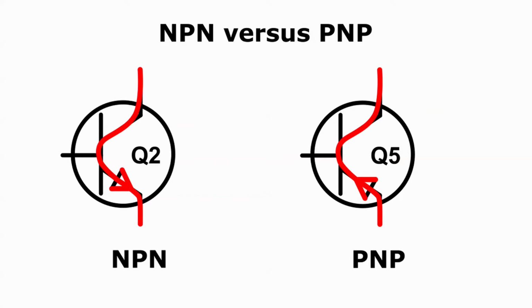In the same way that it's conventional to draw circuits so that signals flow from left to right, it's conventional to have voltages drop as one goes from top to bottom. The NPN transistor shown here is consistent with those conventions. Current flows through the main pathway in the same direction as the voltage drop, from top to bottom.